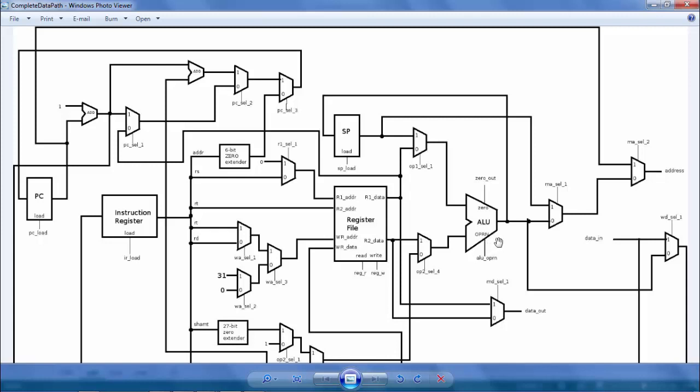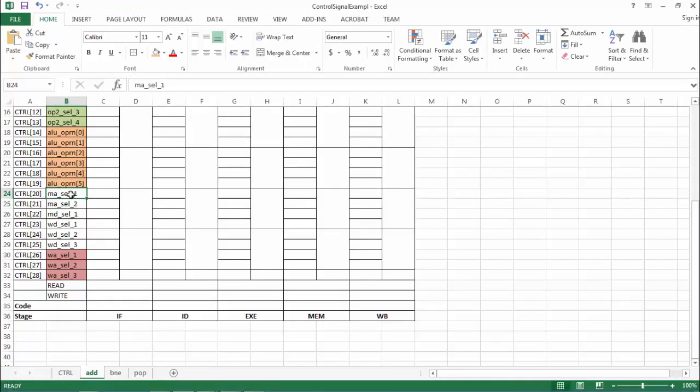If we are executing a load word or store word instruction, then this ALU is computing that address, and that address has to follow through and be sent out to the memory device as an address, right? And if we are doing a push and pop kind of operation, then the stack pointer register is the source of that address for the memory. So that too becomes a group for me. So let's make them a group.